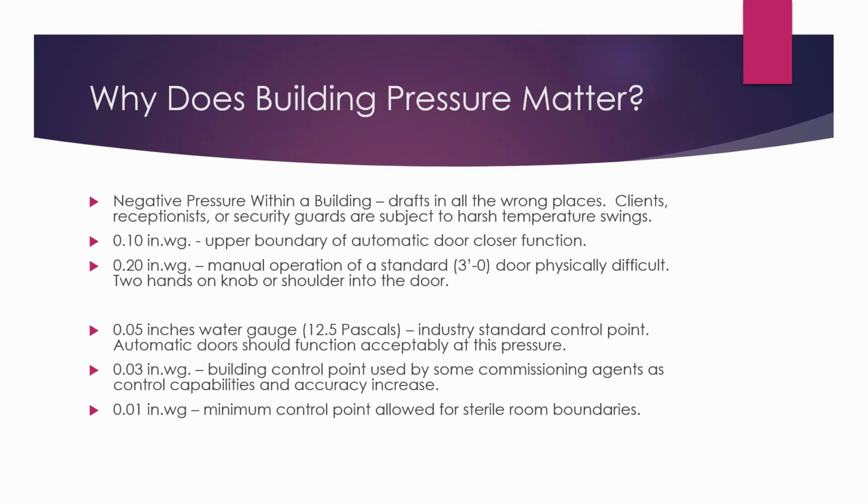At 1/10 of an inch of static pressure, we're at the upper boundary that an automatic door closer can function. At 0.2 inches of static pressure, manual operation of a standard 3/0 door is physically difficult. You've got to pull it shut with 2 hands or put your shoulder into the door to make it work.